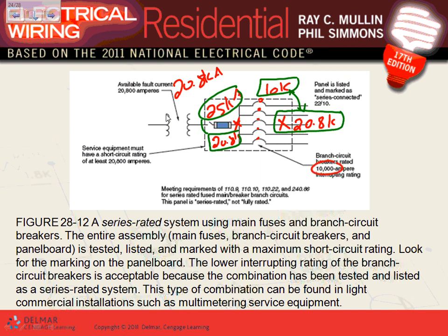Yep. Let's go to the subs. How about here? If I have a short circuit right here, I calculated 20.8. Anything in this panel is 20.8. If I have 20.8 here, but my circuit breaker is rated for 10, would that circuit breaker be able to handle it? No. So that's what they call it. Then the ones smarter than Chad came up with the series rated.